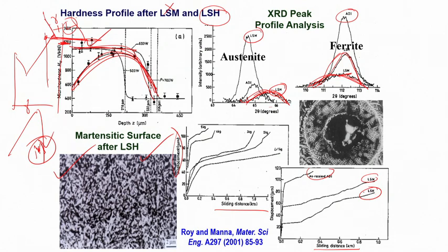So if I start with austempered ductile iron stock of the solid, and if I do surface hardening and we don't allow melt to be formed, then we end up creating not only higher hardness because of martensitic transformation, but also residual compressive stress, and as a result the wear damage or wear loss will be least when we have a hardened surface compared to either as received austempered ductile iron or after surface melting.